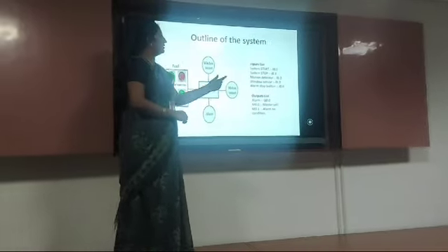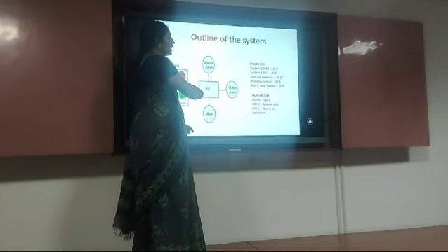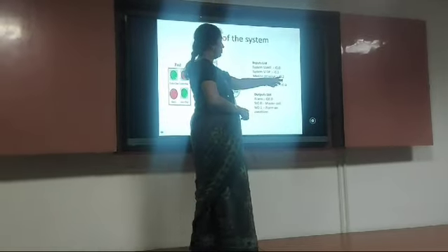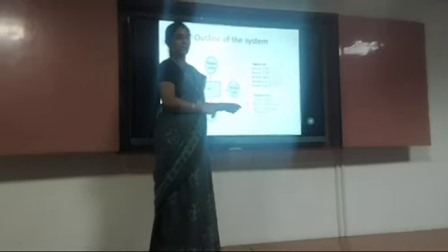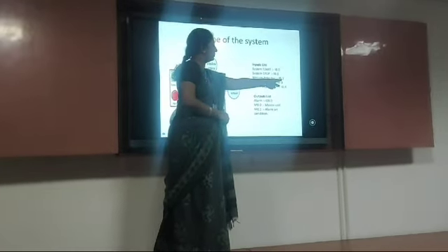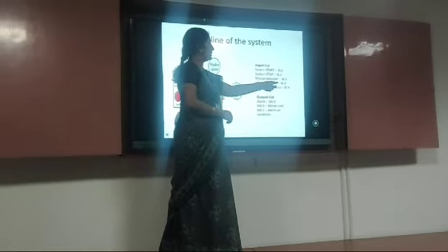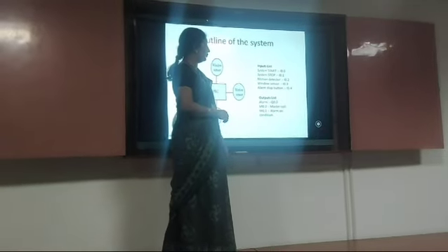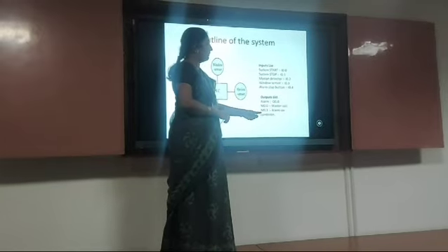And I have listed the inputs here. The inputs are the start of the entire system and the stop for the entire system, I0.0 and I0.1, and the motion detector, that is, if a burglar has entered inside, you are going to get a signal from I0.2, window sensor for I0.3, alarm stop button at I0.4, and the outputs are going to be alarm, master coil and alarm on condition.